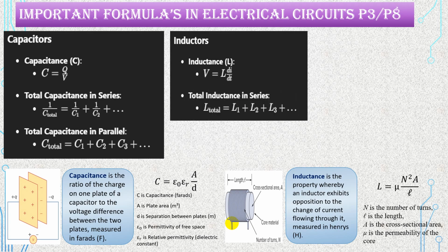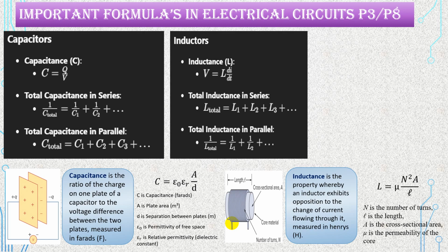It is quite opposite. Capacitance and inductance are quite opposite, and inductance is the same as resistance: L1 plus L2 plus L3 in series, and in parallel, 1 by L1 plus 1 by L2 plus 1 by L3, like this it will come.